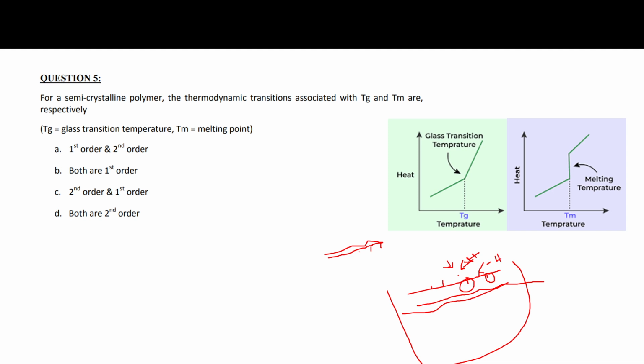After that, if you heat the polymer sample more and more, the small side chains start vibrating or moving against each other. Then if you apply more heat, a temperature comes where your polymer becomes glassy to rubbery. That means the polymer chains now start to move relative to each other.